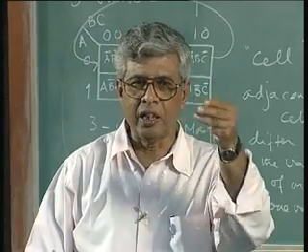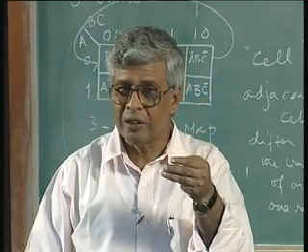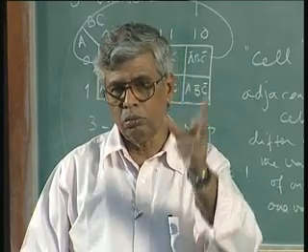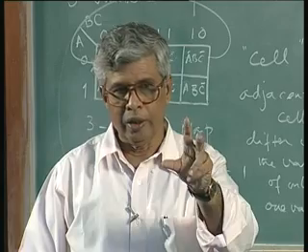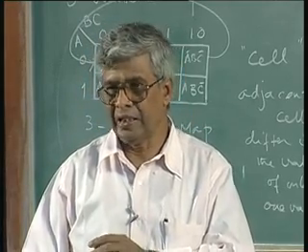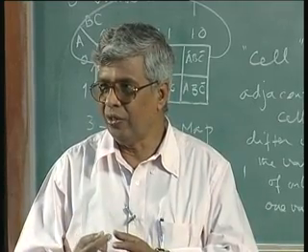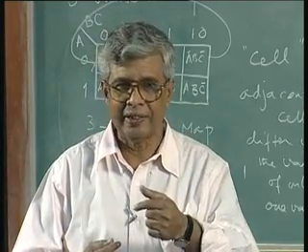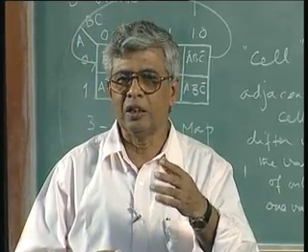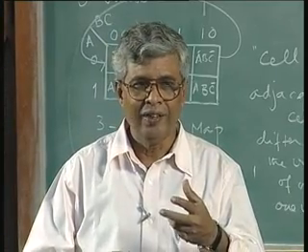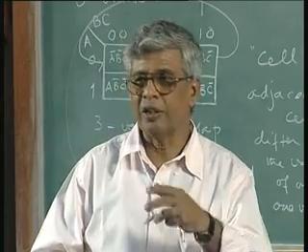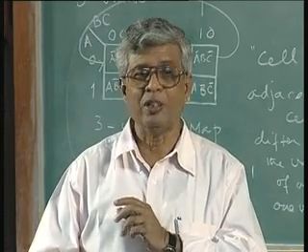Each of these cells has 3 variables. I have knocked off one of the variables, so 3-variable terms have been reduced to one 2-variable term. That is the simplification procedure, nothing very great about it. All we have done is identify the adjacent cells where ones are marked and find out which variables are constant and which change between these two cells, and the changing variable is removed.